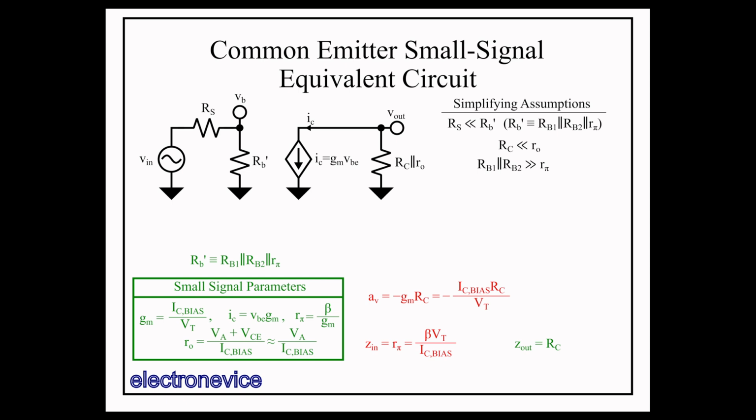Thirdly, the gain is also controlled by the bias current, and we can see that increasing the resistance and the current to increase the gain will increase the voltage drop across the RC resistor, which limits the amount of gain you can get out of the system by VCC. So higher VCCs generally allow you to have higher gains with this particular biasing circuit. Finally, the gain is inversely proportional to absolute temperature, so it will move around with temperature, which is not ideal, and for precision circuits, this effect needs to be managed and mitigated.